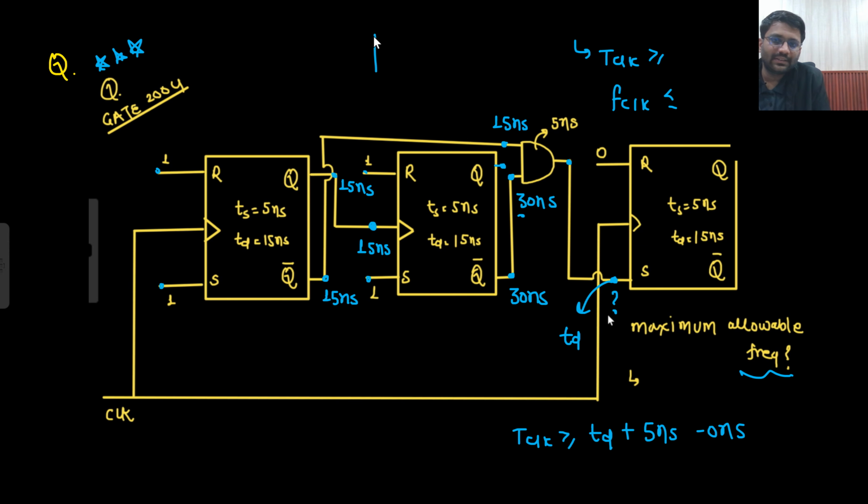So this is an AND gate. He is stable after 15 nanosecond. Now he is waiting for him. That now you have become stable. Yes sir, I have become stable. Now this final output will be stable. So after 30 nanosecond, they will start giving the output. Like he says that, sir, I am stable at 15 nanosecond, but he has to wait for this guy, no? So they will start giving the output after 30 nanosecond, but the gate will say that I am also having a delay of 5 nanosecond. That means the output of this gate will be stable at 35 nanosecond.